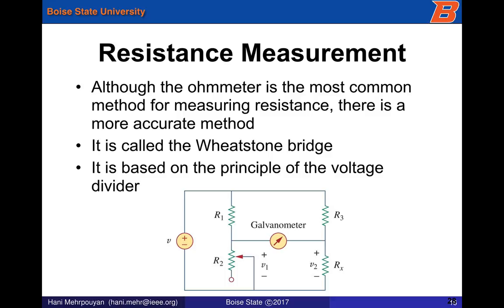Now, we could use this concept to try to actually measure resistance. Obviously, you can measure resistance using a multimeter, and I brought my multimeter to class, and we were able to look at this. However, there is another way we could do this, and that's using a Wheatstone bridge, which I discussed before. So if you have 3 resistances where you know the value, R2, R1, and R3, and yet one of them has to be variable. If you put a galvanometer, which is a very, very sensitive current meter, in between these 2 terminals, and then you connect your